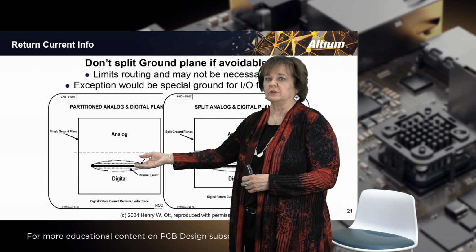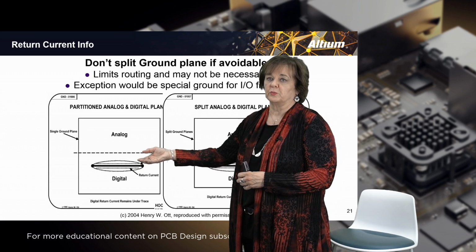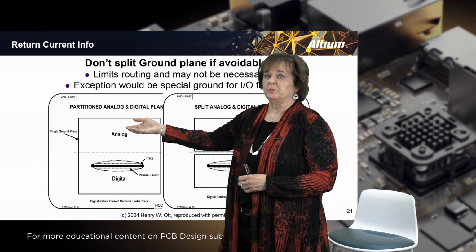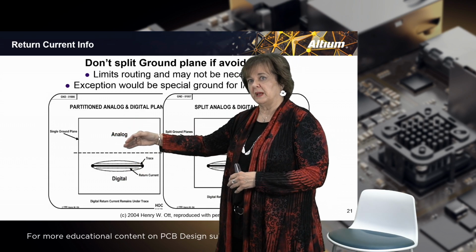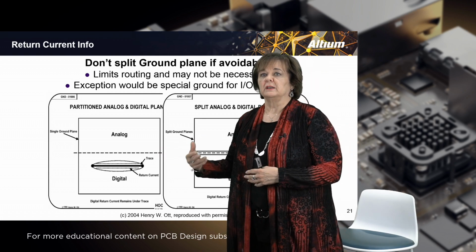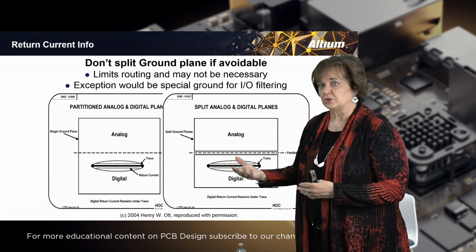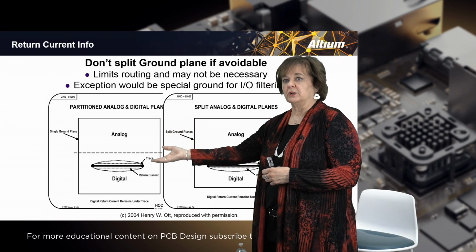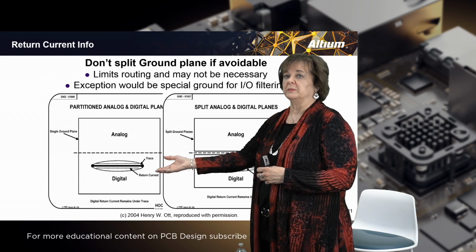the edge. The digital signals are going to follow the signal itself, so the return current is going to be where the signal is. And the analog, if you put it up in the analog region and keep it back from an imaginary line between them, then the two should not interfere with each other, and usually don't interfere with each other. If you have any concerns about that, you can also route them in opposite directions.